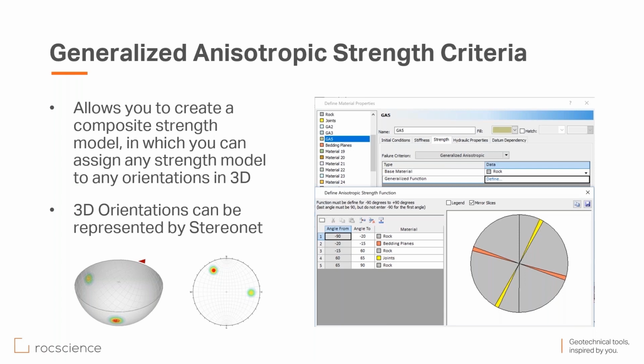Now, when you are looking at the general case of an open pit mine, for example, that is excavated in an area that has this kind of rock, depending on the angle of the cut with respect to the orientations of these beddings and joints, you might have different failure mechanisms. In some cases, you might have a slip along one joint. In another configuration, another cut angle, you might have toppling. So all these configurations can be handled properly using RS3.